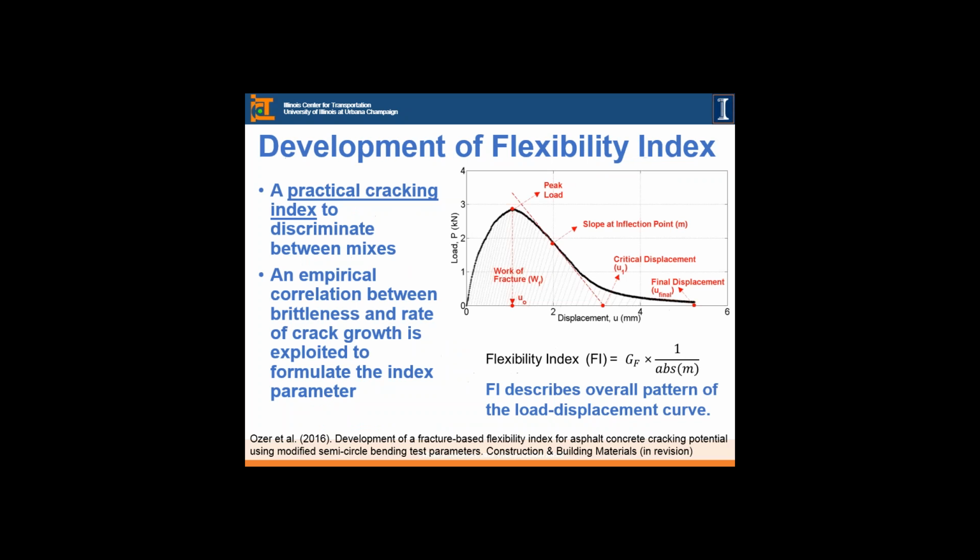In developing this flexibility index, we looked at different test parameters that we can get out of this load displacement curve that define the overall response of the curve. It's a practical cracking index to discriminate the mixes, and we found an empirical correlation between the brittleness and rate of crack growth. We exploited this relationship to formulate the index parameter, and the index parameter was simple. It was dividing the fracture energy by the slope of this curve at the inflection point after the peak. So we believe this FI number describes the overall pattern of the load displacement curve better than the fracture energy.